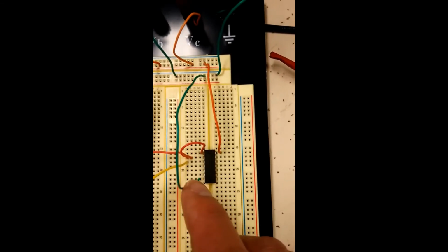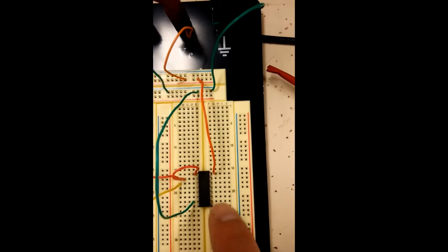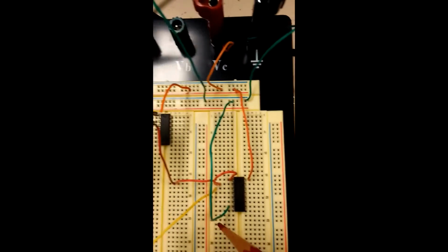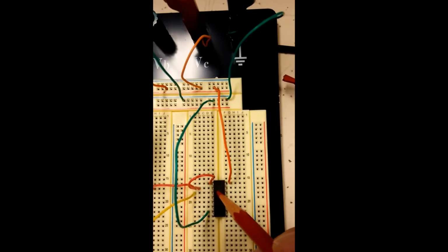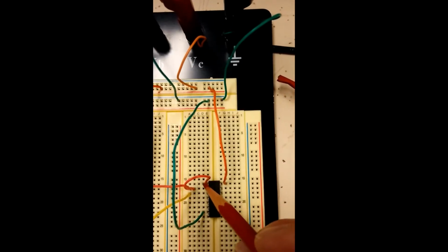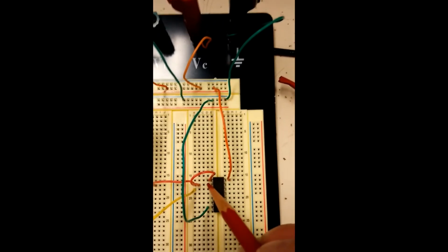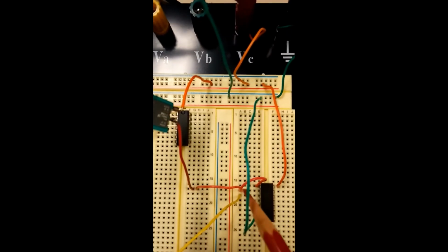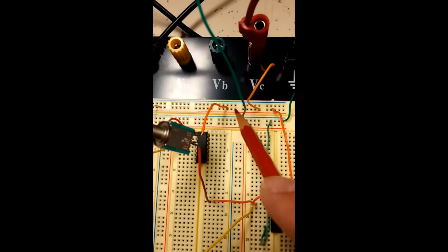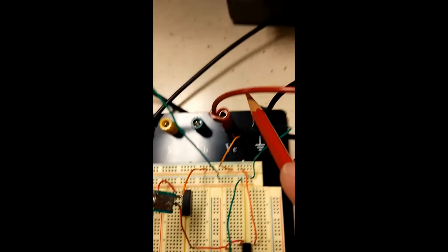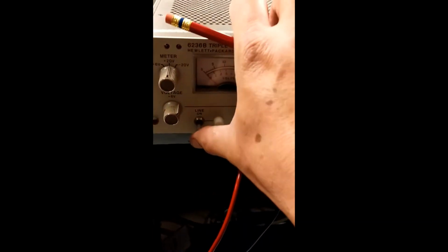This is the circuit that we built last time. This is the 4011, and we use pins 1 and 2 as input A and input B, and they are connected. Then we have the power, and the push-on switch to 5 volts. This is 5 volts from our power supply here, so we can turn on the power supply. We already checked it's 5 volts.